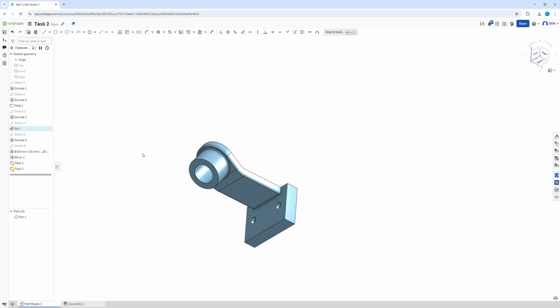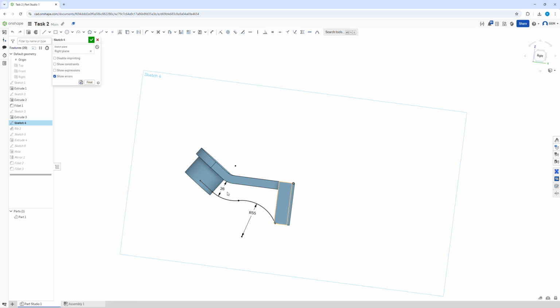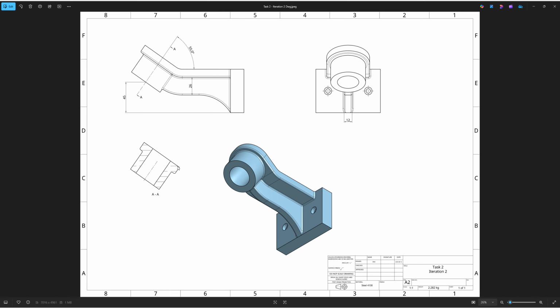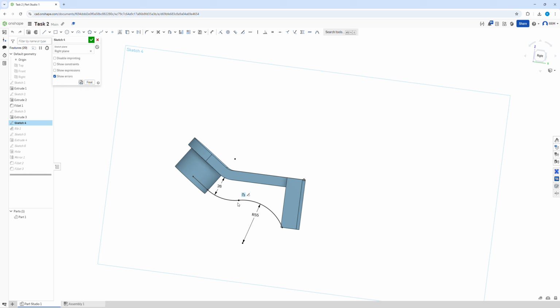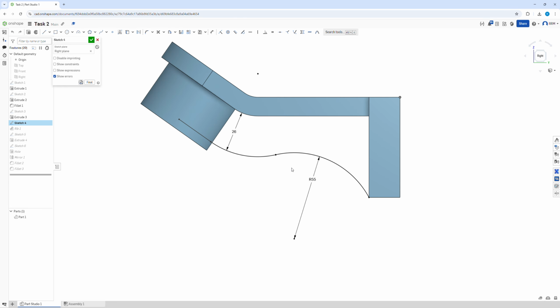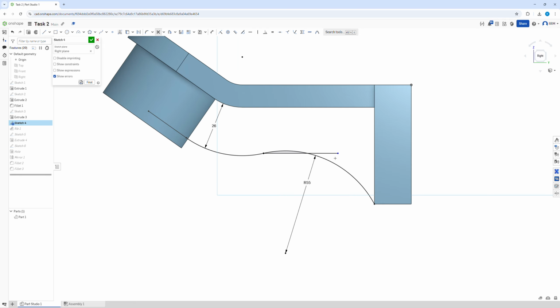So we go back into our rib. What is different here? So we've got the 2 sections. Let's check it compared to the drawing. It's now got, it goes flat and then it goes tangent. So what we can do is we can go normal 2, and we can get our line tool. We can take it from this dot, go across parallel. We can then trim that off by pressing M on the keyboard, trim that end bit, trim this end bit, and that gives us a flat section in the middle.